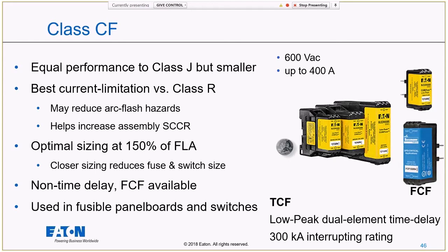The only thing that makes it different than the Class J is its form factor, right? Part of the definition of a Class J fuse is you have to fit in a Class J holder, and this does not meet that definition. This is our plug-in fuse. Hopefully you're familiar with this. We've got the examples here where we show it just in the holder. We have it in a switch device as well.